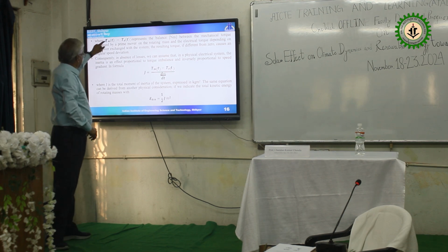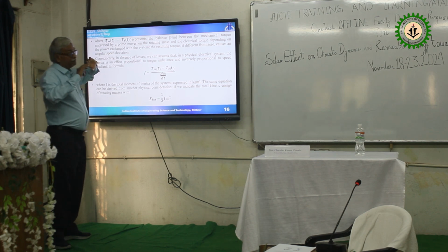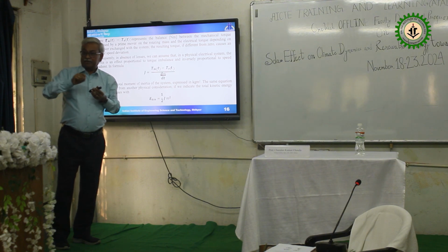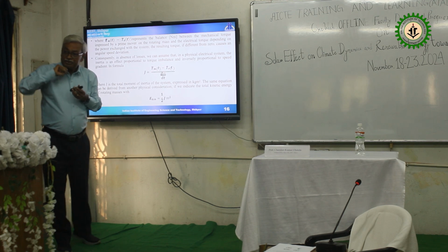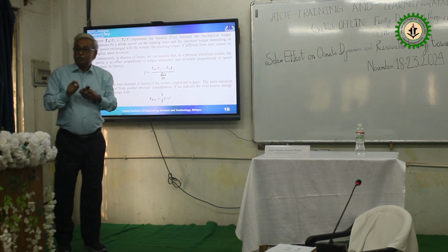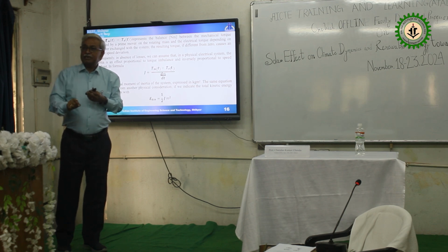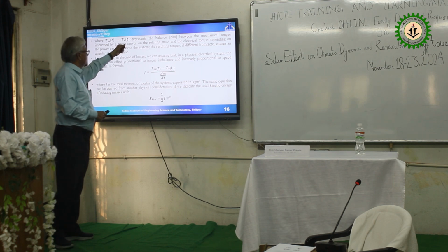I have intentionally given T because when you put in renewable energy it is a time dependent function. Solar irradiance, solar insolation is a time dependent function. So solar generation is a time dependent function. So inertia is continuously changing depending on the supply. So this inertia cannot be a time independent function. So intentionally I have given it as a time dependent function.